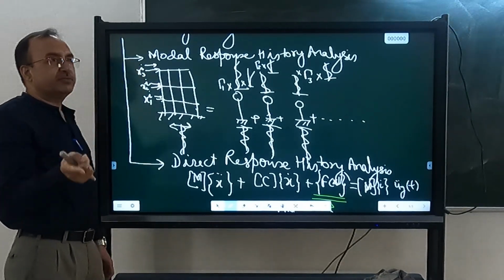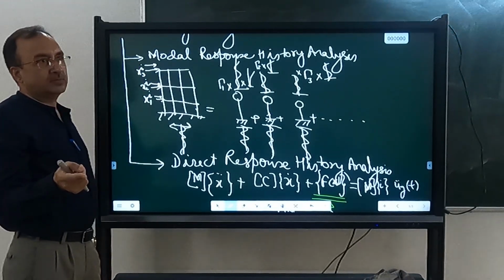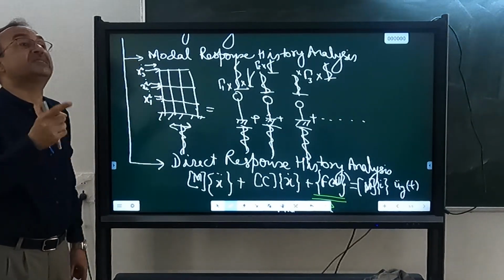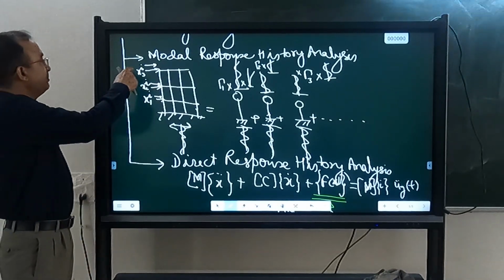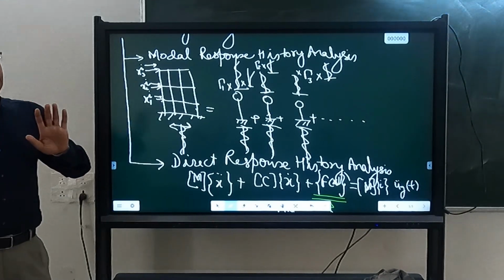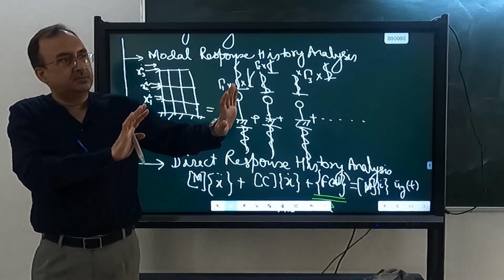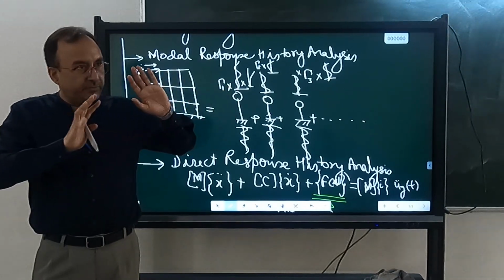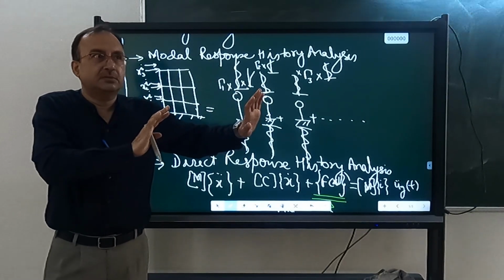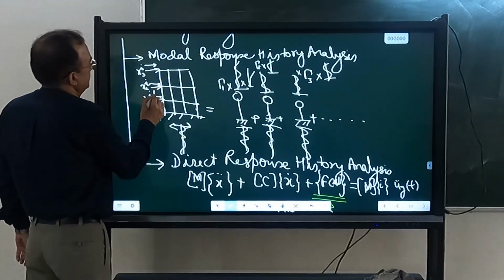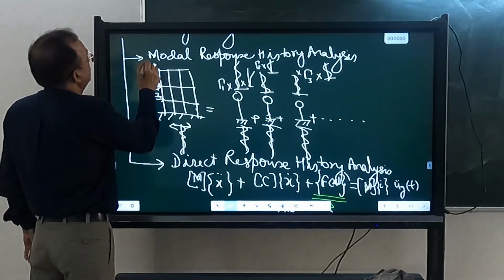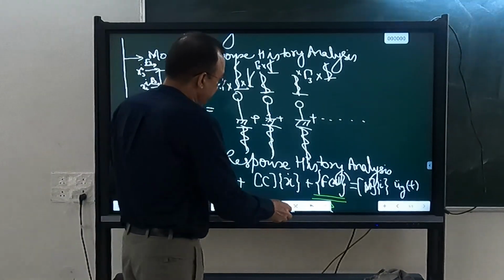That force you will measure from the load side. At the previous step, at which you have got the displacements, you will apply those displacements on your structure, and for applying that, you have to apply some force, F1, F2, F3, that will give you this value.